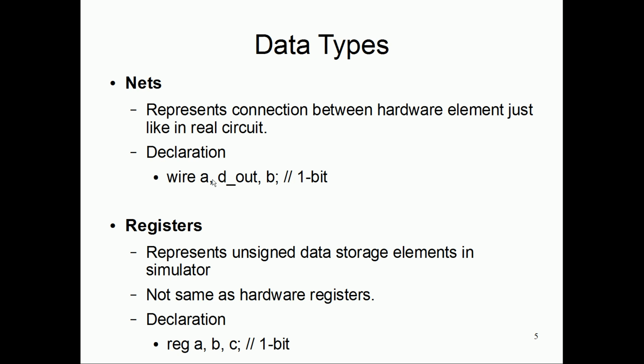And a register, on the other hand, represents an unsigned data storage element in the simulator. It is not the same as the hardware register that we'll be learning about later in the digital design section. Just keep that in mind. When you do a reg A, we're not talking about a sequential circuit element register, it is just an unsigned storage element in the simulator.